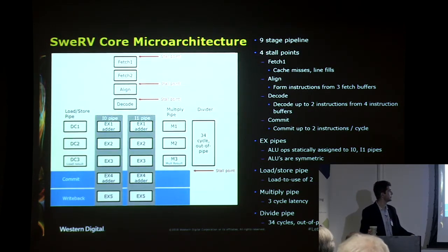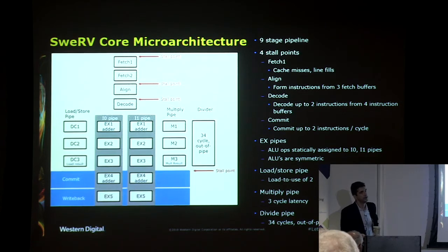And the second question is the load store pipe. Load-to-use penalty is 2 cycles, which makes a lot of sense. Then you didn't say anything about the cache itself: is it 1 read port or 1 write port? So what happens if you have a load and a store instruction? You dispatch 2 instructions, right? Does your pipeline do stores? It does, it has to. And then when you do the commit, do you do it in order, programming order, or?